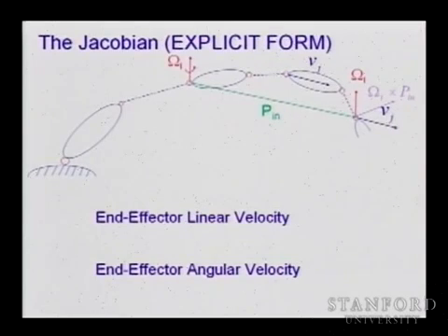And once you understand this model, you are going to be able to look at a robot and see the Jacobian automatically. You look at the machine and you see the model automatically through this explicit form that we will develop to compute those linear velocities and angular velocities through the analysis of the contribution of each axis to the final resulting velocities.